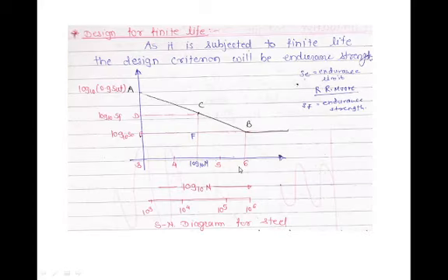Now that is for infinite life. For finite life, it is the endurance strength, that is equal to Sf. For that we will use the R. R. Moore test. The graph is generated by using the R. R. Moore test. The portion from 3 to 6 is for finite life, and from 6 onward it becomes the infinite life.